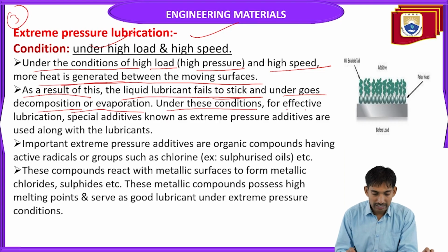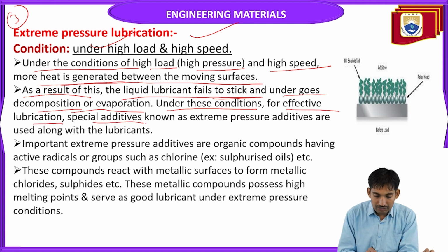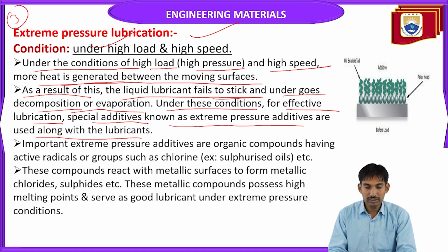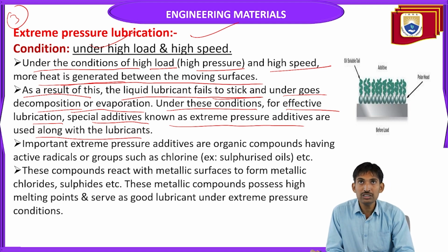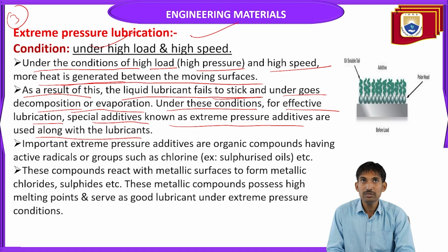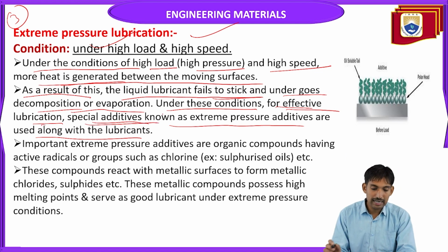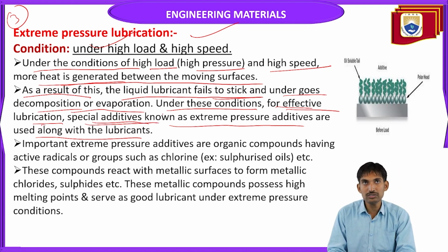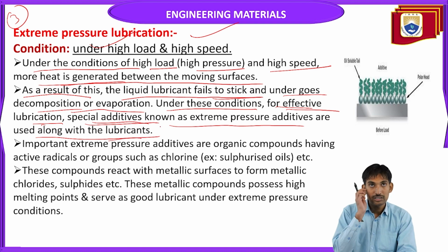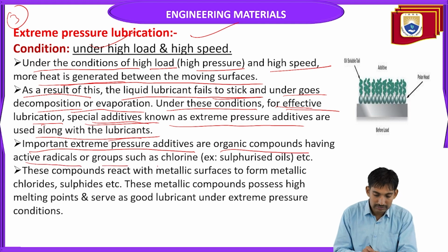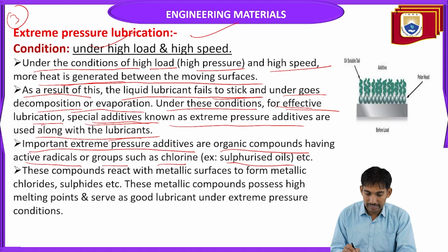Under these conditions, for effective lubrication, special additives known as extreme pressure additives are used along with the lubricants. To stop the decomposition or evaporation, you have to add some chemical additives to the lubricant oil.